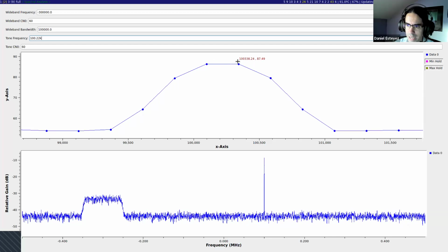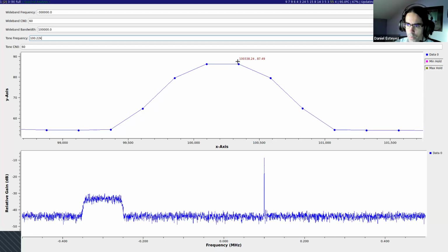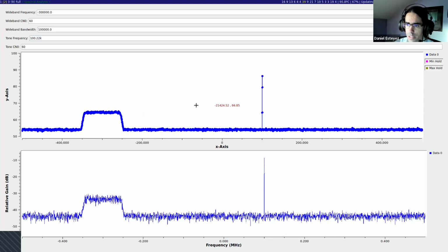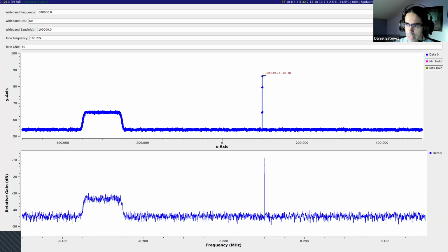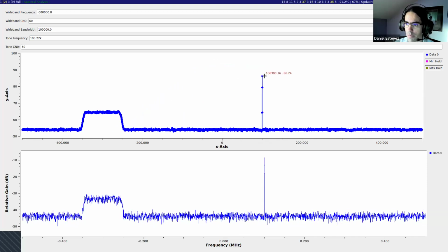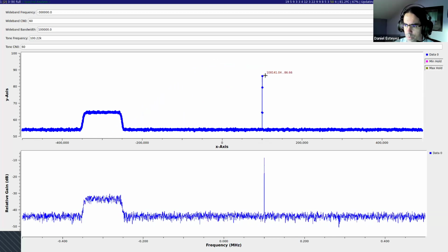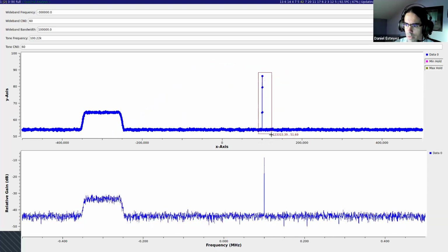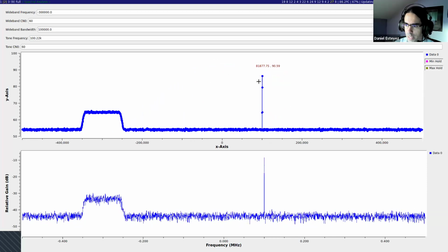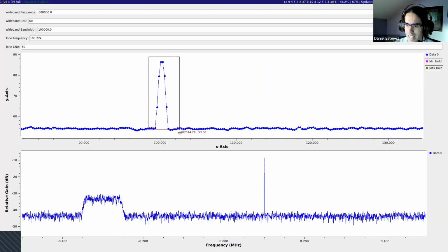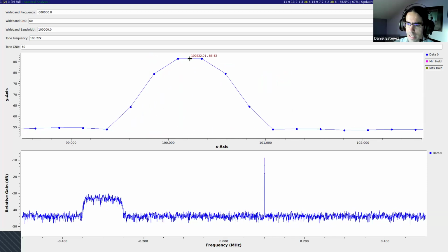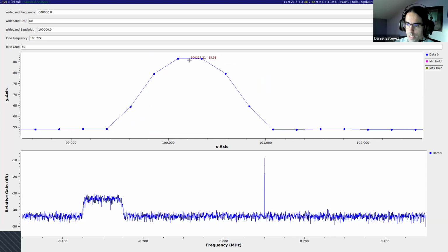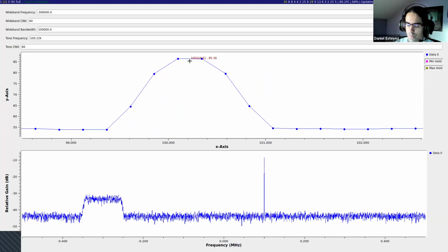That is called scalloping losses. So whenever you see the spectrum of a signal and you say, hey, my signal is something I see on the spectrum, that might not be completely right, because if it's a narrowband signal like this, depending on how the signal is aligned with the FFT bins, it might have some scalloping losses, as in this example.